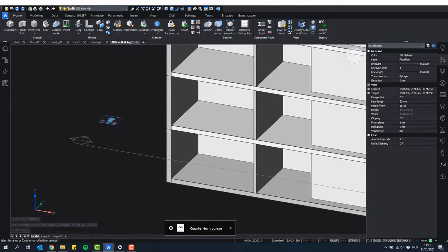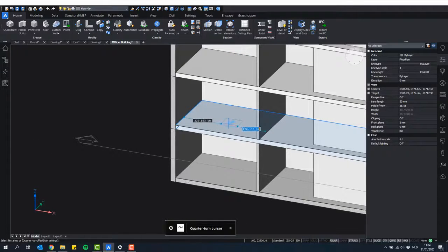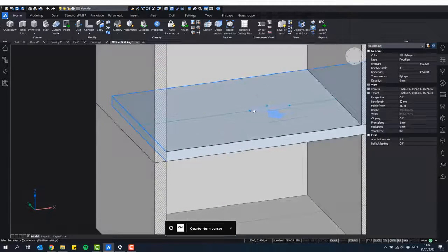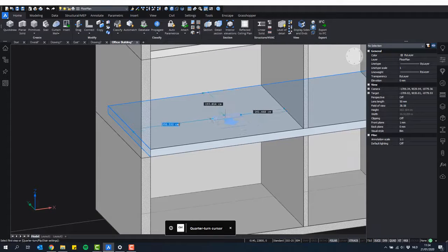The thing about this cursor is that it will snap to existing floor slabs. Let's say if I move over here, it snaps to this floor slab, this one, and it will snap to existing walls around it. So let's say I move my cursor here, it snaps to this wall. As you can see with the control tip down below, you can press control or tap control a few times to change the direction of your stair. In this case, I want to create a staircase that goes along this wall. So I left click once I have my location here.